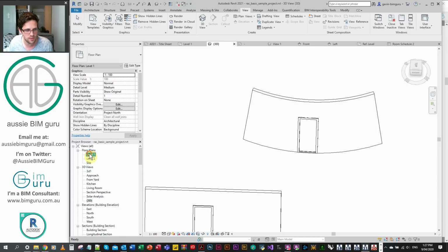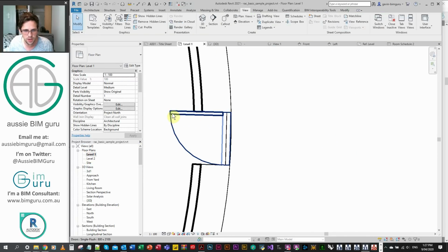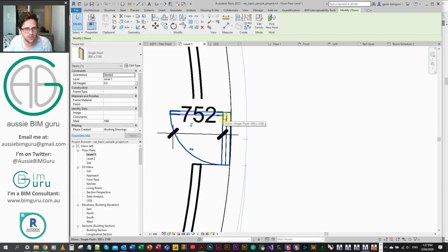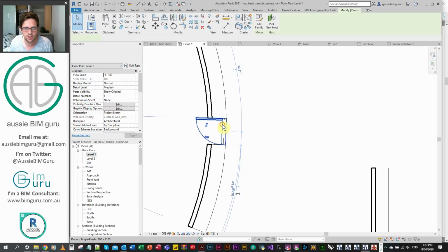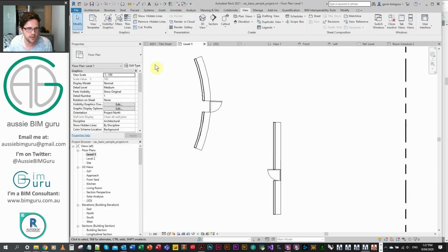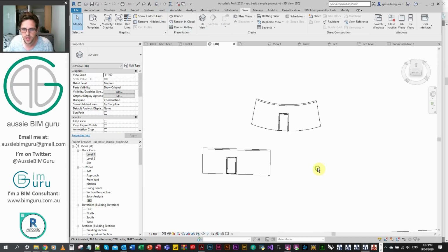And I think as well as that, if you go to like a floor plan, I reckon you still get the symbology cast in the floor plan. I assume it's still parallel. No, it's not. So that is one constraint that you also get, I believe, that all the symbology is also raking. So you don't get the perfect graphic representation of your element in floor plan, unfortunately. I mean, you do technically get the right swing depth, but it might look a bit strange if you put dimensions on it in floor plan. So pretty cool.